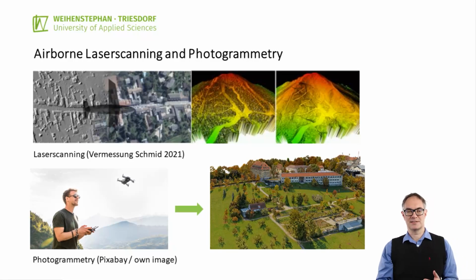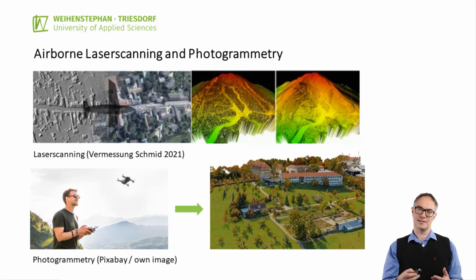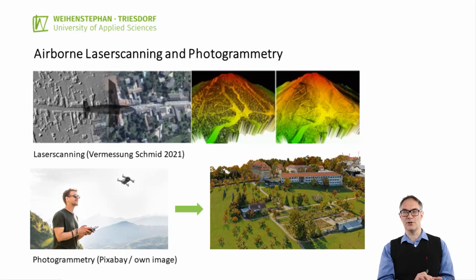And the reflection is giving the exact distance and angle to the ground point and the color of that point. And by this way, you collect millions of points with the exact location and color, and you get a model like the model in the bottom right. This is not a photo, it is a point cloud made of millions of points with each individual color coming together to a representation of the surface.